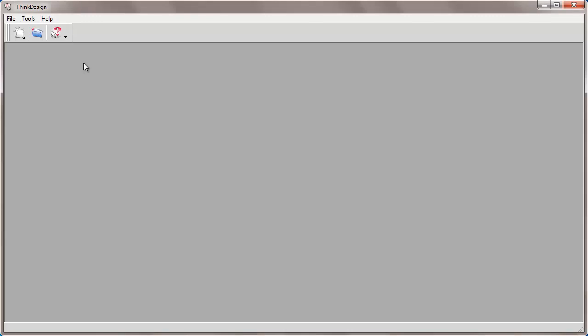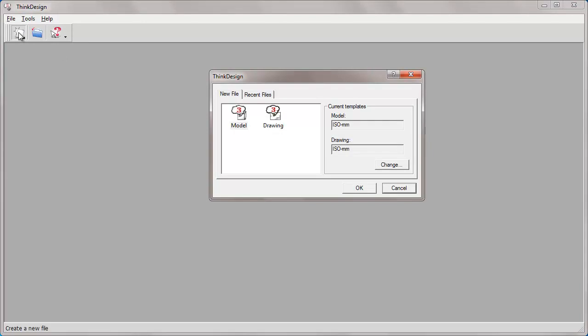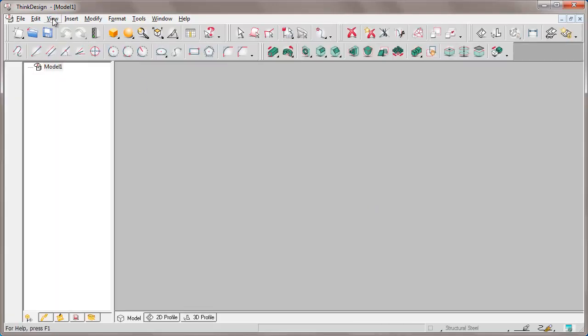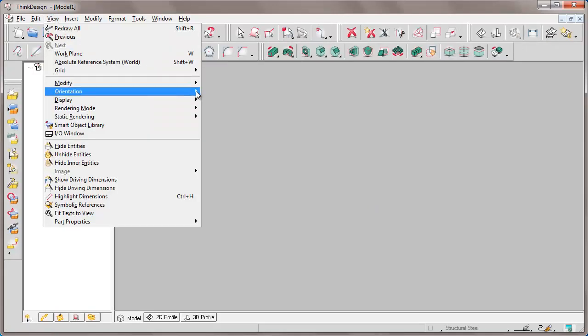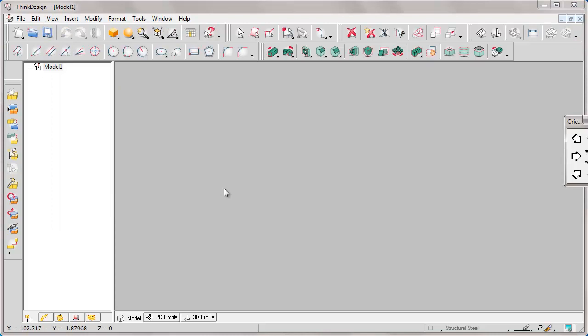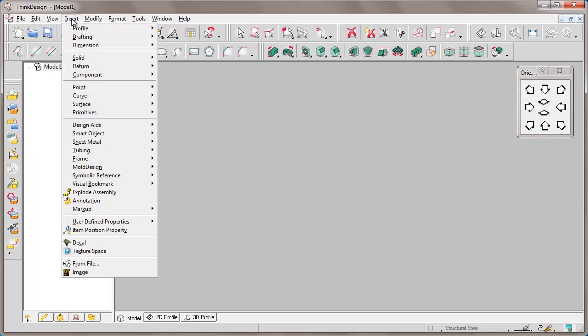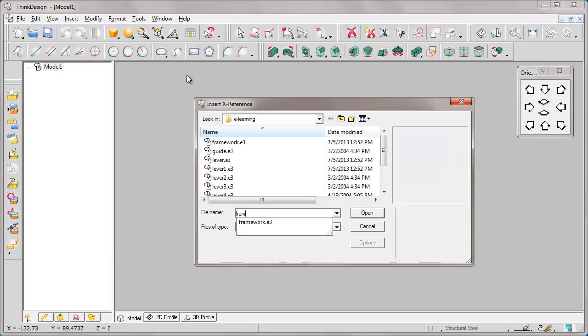The theme of this e-tutorial is to show how the solid mating command is used, a command allowing us to place a solid in relation to other ones by applying geometric constraints between the entities composing the solids. In particular, we will have a look at the different options of this command, while later we'll deal with the multiple mating command and we'll see how to check any possible interferences and collisions between objects.